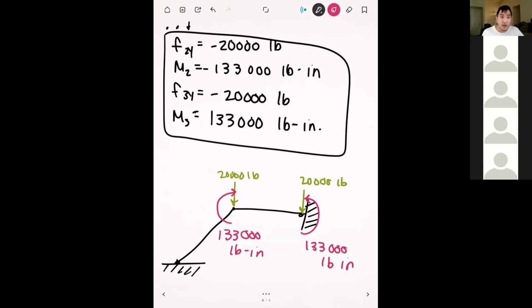And so, by applying our principle of equivalent work, we've converted that distributed load into these nodal loads, and now we can just follow the same process as we did before. From here, we can write out the element stiffness matrices for all the elements. There's only 2 in this case, and then assemble the global system, apply our boundary conditions, and then we can solve. All right, any questions on this? Okay.